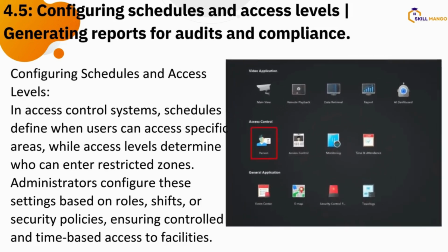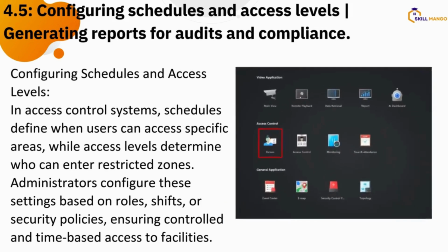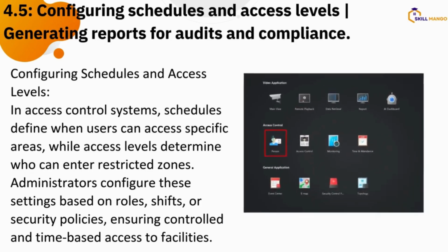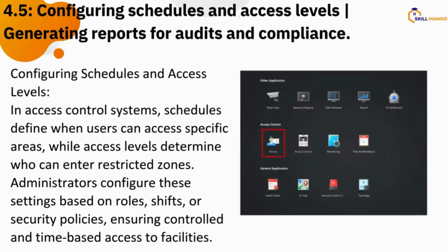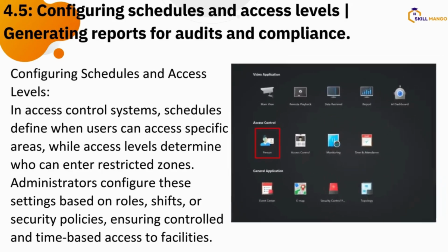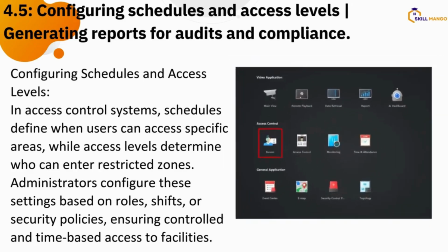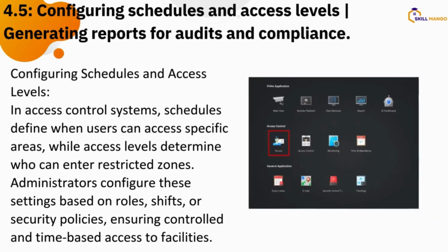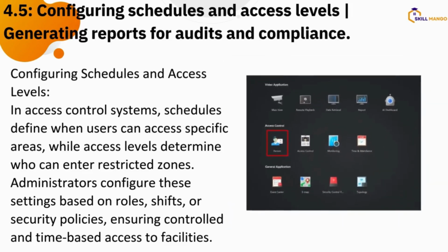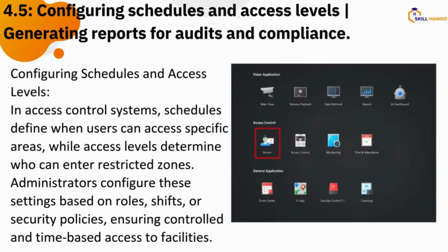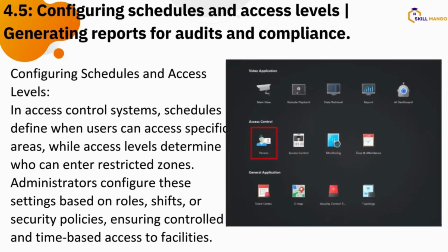This is very important because the idea is control, and the system is the one that controls the hardware, which is the reader. So as an administrator, you launch your software and set your rules. We're going to check all that practically. Set all your rules, set your privileges for users, and synchronize it to the system, to the hardware outside by the door, so it can understand and carry out the instructions you have given it. All this will be done on the IVMS 4200, or IVMS 4200 AC or 5200.